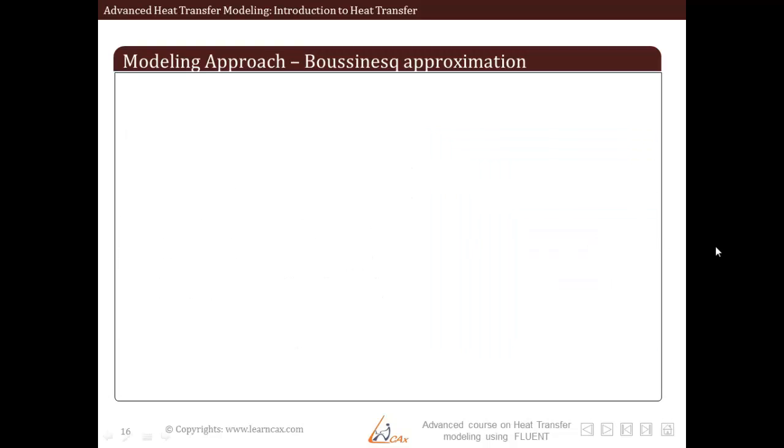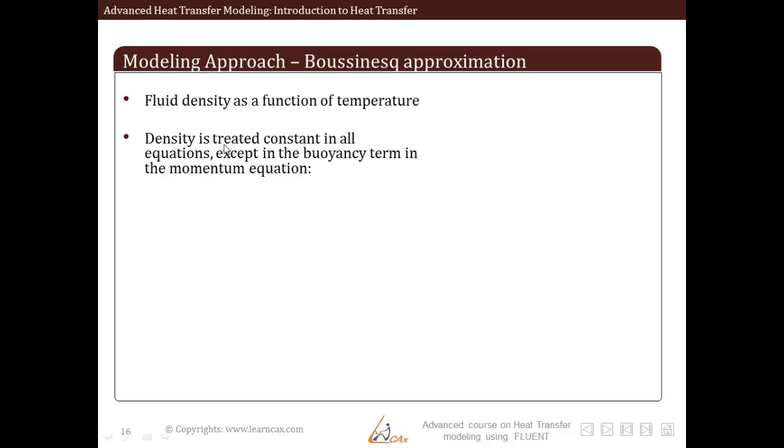Now that we have discussed the steps involved in setting up a heat transfer problem, we will take one topic at a time and go into detail discussing the modeling approach associated with that particular topic. So the first is the Boussinesq approximation. The Boussinesq approximation is used to define density as a function of temperature, and in this case the density